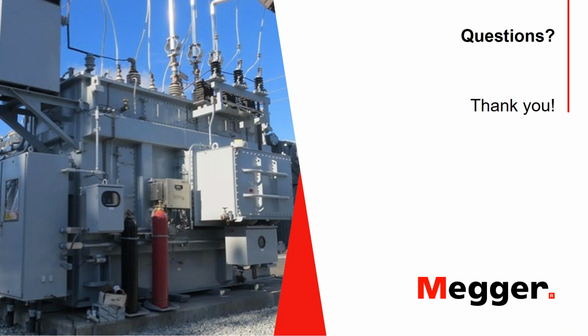Thank you. Samir, in what standard can we find the 2% resistance tolerance between phases? So, several industry standards discuss the 2% tolerance across winding resistances. Some references I would recommend the attendees to review would be the IEEE standard C57.152, which is the diagnostic guide for transformer testing. In addition, you have the IEEE C57.12.90, which is the standard test code for transformer testing. And you can also review the NETA standards, which are the acceptance testing specification, that's the ATS, and the maintenance testing specification. So they will have more discussions on the 2% variation between windings. Those are good references I would recommend the attendees to review.